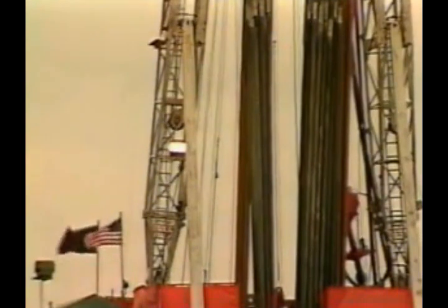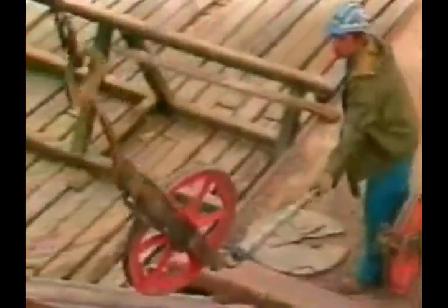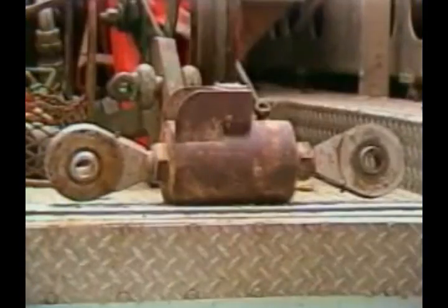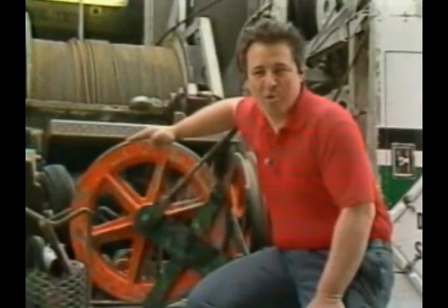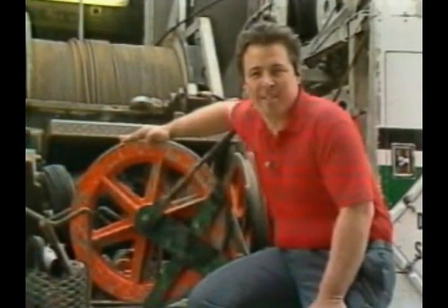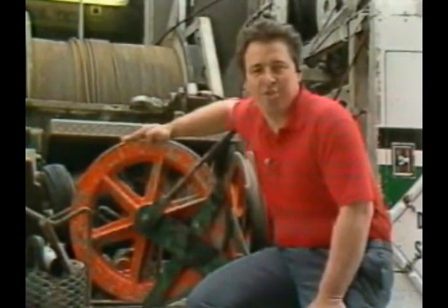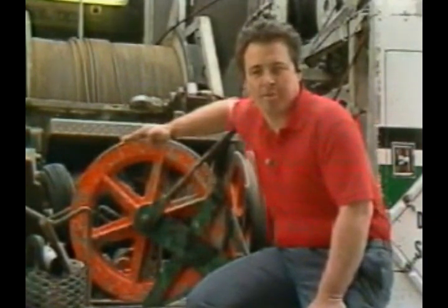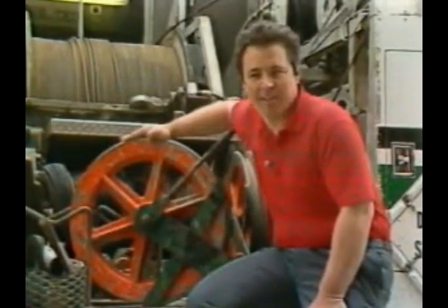Once the drill pipe is clear of the rotary table, the next step is to rig up. This procedure includes hanging the sheave wheels, threading the cable through under the bottom wheel and over the top wheel, then attaching the cable head to the uppermost tool and raising the tool string. A cable tension gauge is always used and may be attached to either the upper or lower sheave wheel. It is important to remember that these sheave wheels will be points of maximum stress during the logging run. Care should always be taken to see that they are well secured. Final steps in rigging up can now begin.